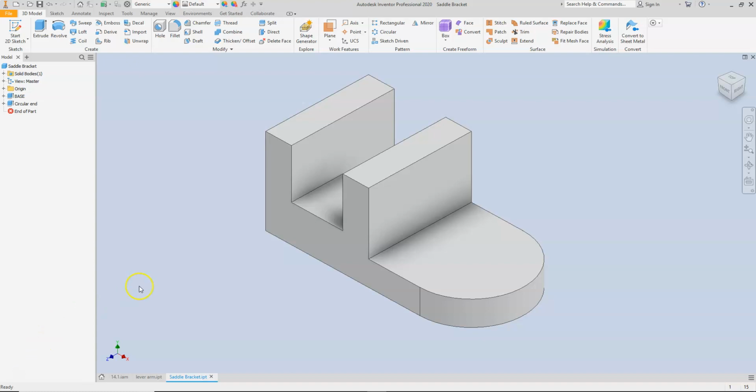The next thing we're going to do is place a feature on this piece right here. We're going to be using the hole command in order to do this, and I'm going to show you how to point to the actual plane where we're going to be placing this. We're going to be using the circles. Since they are concentric and they share the same center point, we're going to see that reference symbol pop up as we're placing this hole.